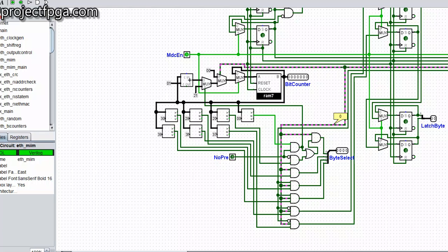That is to say, for any of these byte select signals to come on, it must be either a read operation, a write operation, or a scan operation. See, the in progress is in every single signal. So if the in progress is off, none of the byte select signals is going to be on. That is essentially what the in progress does. It marks that a particular operation is in progress.